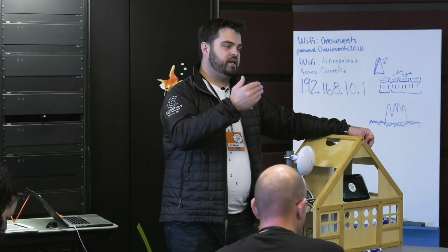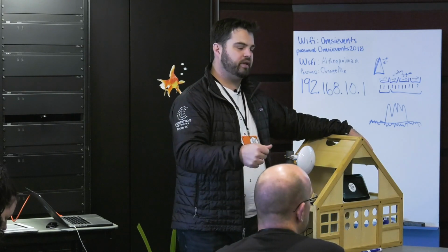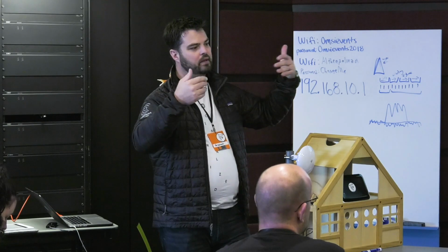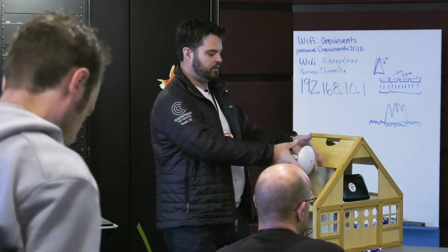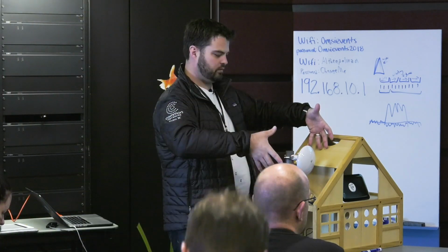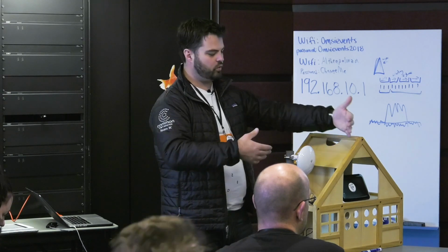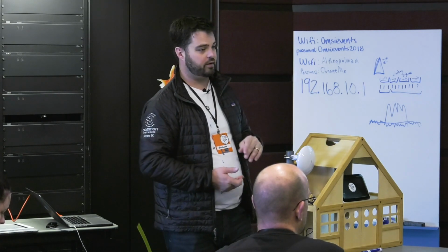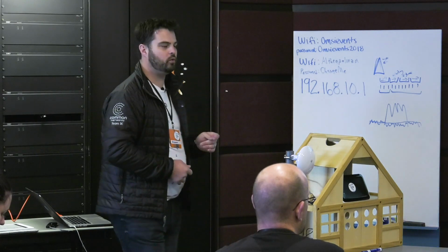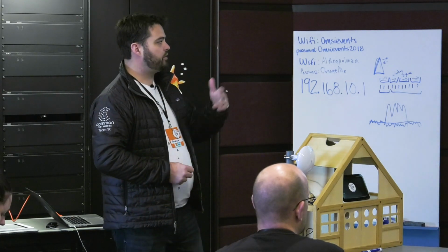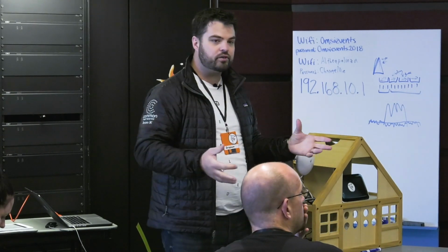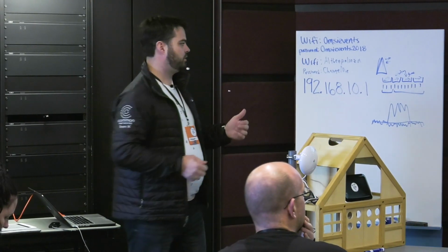Typically when you're looking at it, weight is a concern, but probably an even bigger concern is wind loading. The more surface area of antennas you're putting on there, the more wind it's going to catch, and that's when it'll really start to test the structural integrity of the tower. That's when the wind is hitting it. So there are things that you can do to increase the structural integrity of the tower, things like adding guy wires. Guy wires, if you're unfamiliar,